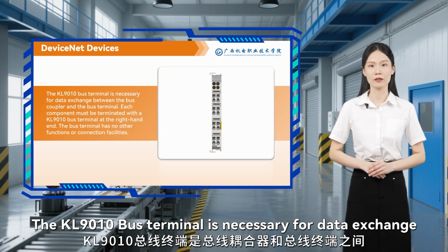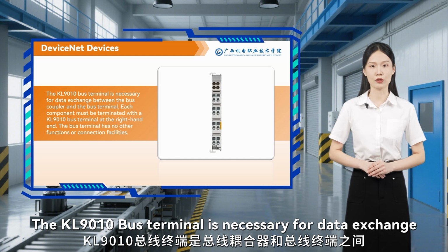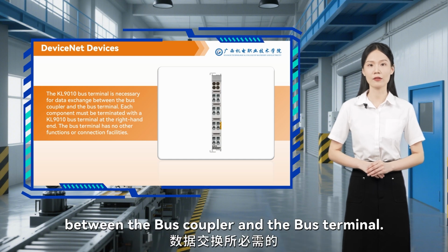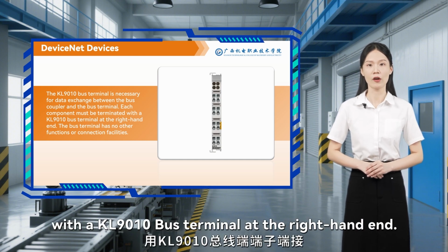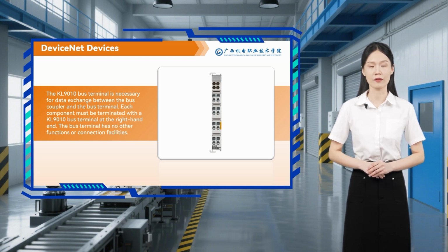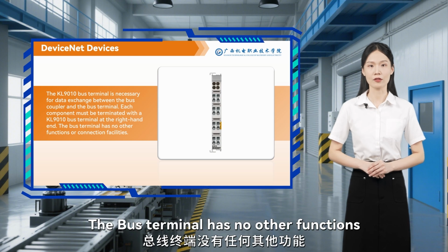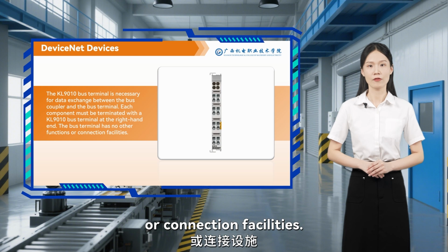The KL9010 bus terminal is necessary for data exchange between the bus coupler and the bus terminal. Each component must be terminated with a KL9010 bus terminal at the right hand end. The bus terminal has no other functions or connection facilities.